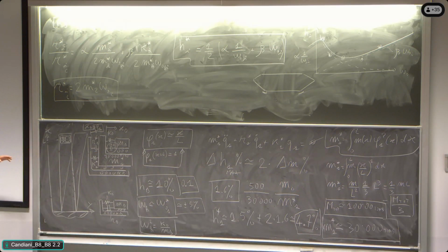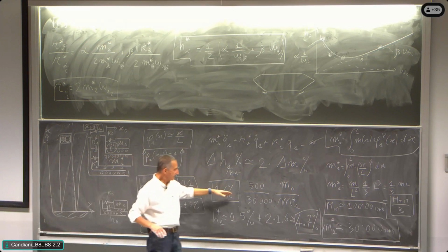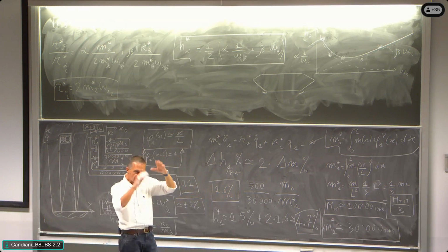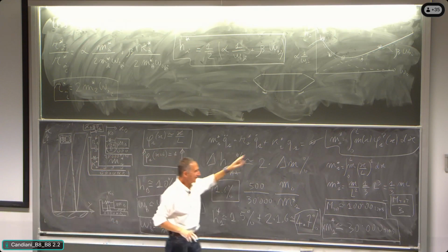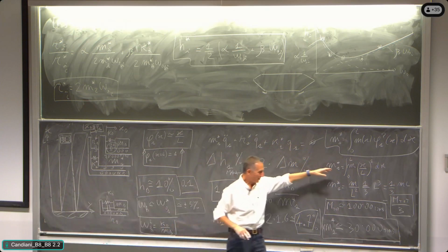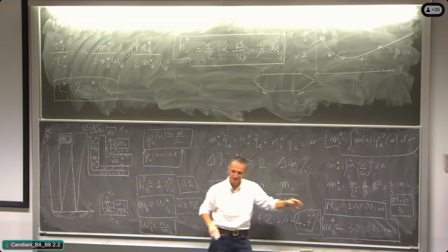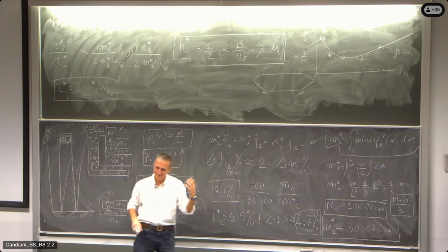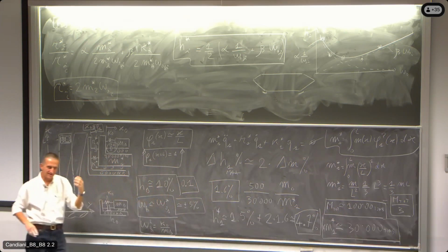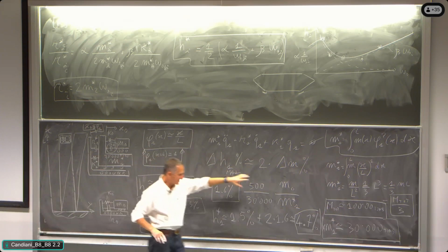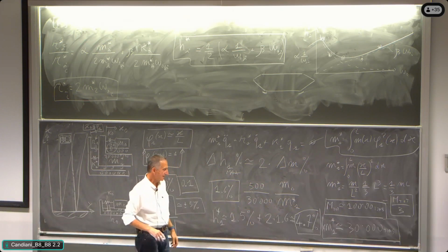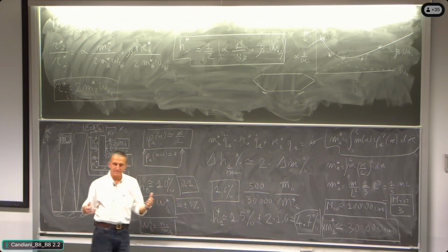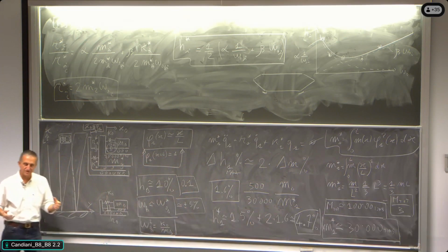And so the idea was using an object with a mass that is in the order of, we said, 1.6% of the modal mass, be careful. 1.6%, not of the total of the 100,000 tons of the building, of course, okay? 1.6%, so this percentage is over the modal mass, all right? So this is the rule of thumb of dimensioning of the tuned mass damper,